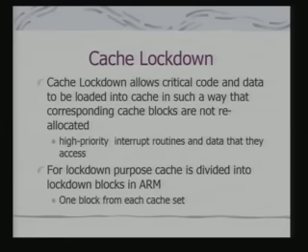This cache lockdown is the other point that I was discussing already, that I would like to have some critical code and data loaded into cache in such a way that corresponding cache blocks are not reallocated. Okay? Because these will be repeatedly used. In fact, the whole purpose of using SPM also is something similar. In the SPM also we can have the critical code which will never be replaced because it is part of your memory itself, memory map itself.